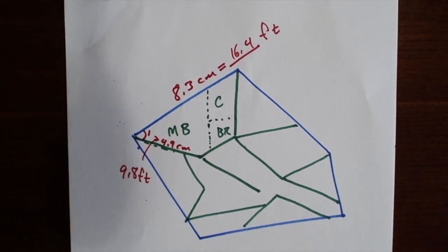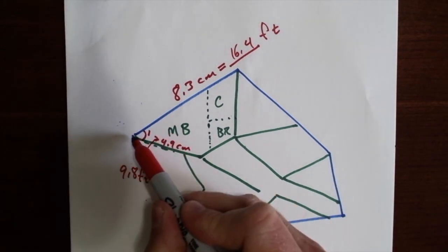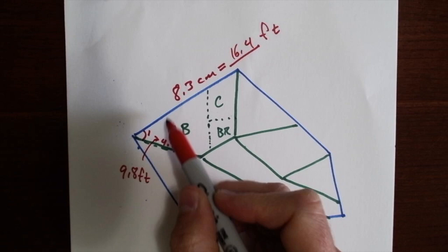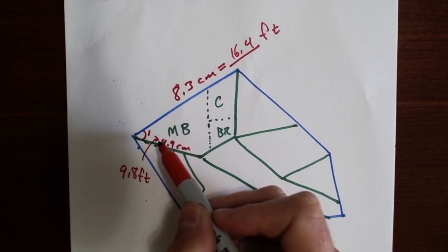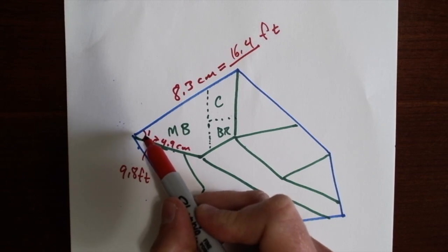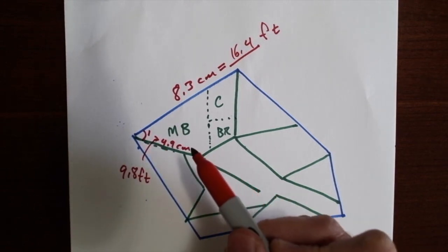If your house has right angles, well, that's really simple for a builder to set up and say all the angles are going to be right angles. It's really simple, it's straightforward. Most builders have really straightforward ways of doing it, namely a 3, 4, 5 setup. You measure 3 feet this way, 4 feet that way. If this last measurement across this way is 5 feet, you have a right angle. But we don't want right angles, so we're actually going to have to figure out what all these measurements need to be so the house is built properly.